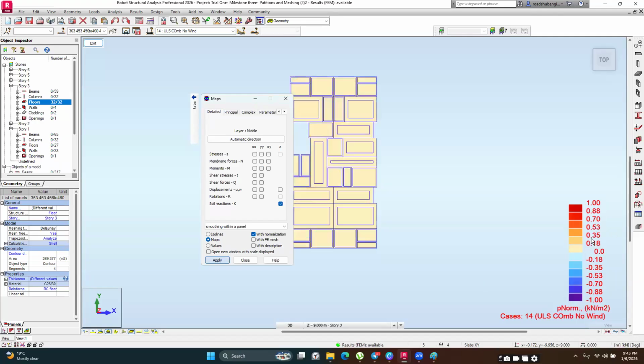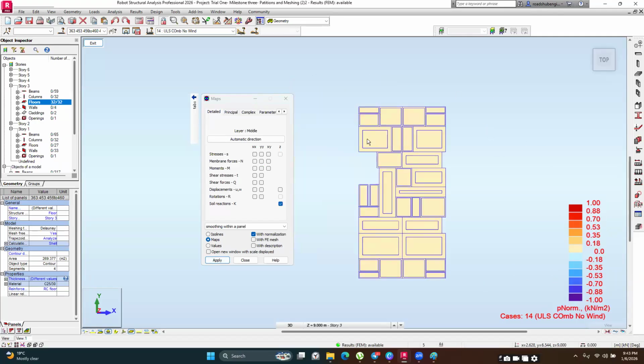At this point, it's going to be 0, because we have not assigned any supports or any planar support for this slab. But when we get to analyze our mat foundation, we are going to compare the maximum pressure that we are getting to the bearing capacity. So you're going to ensure that the maximum pressure we are getting is lower than the allowable bearing capacity that we have.